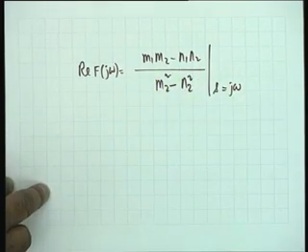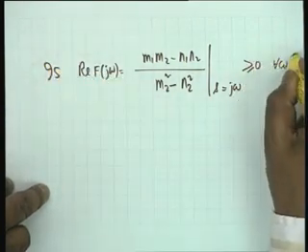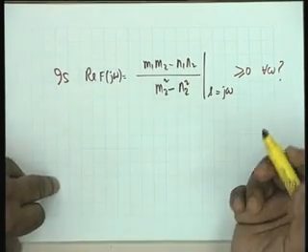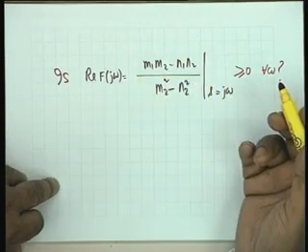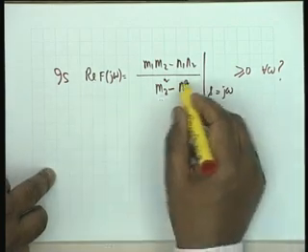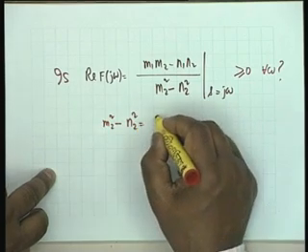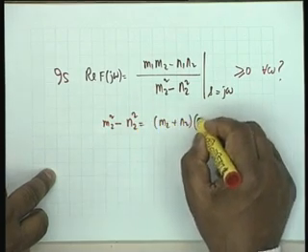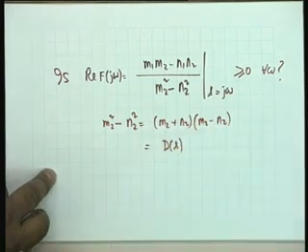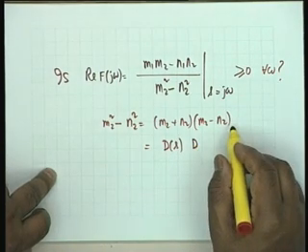We have to see whether the question that we ask is: is this greater than or equal to 0 for all omega? That is what we are asking, right. Given the function, I can identify m1, m2, n1, n2, I can form this and then test this, but this testing is further simplified by the fact that the denominator of this, that is m2 squared minus n2 squared, is m2 plus n2 times m2 minus n2, which is equal to the denominator of the given function d of s multiplied by d of, what is this in terms of d?